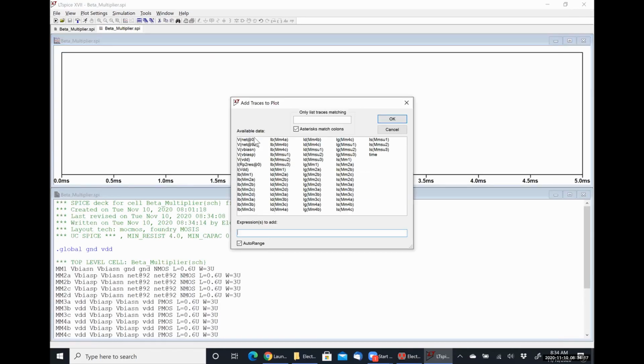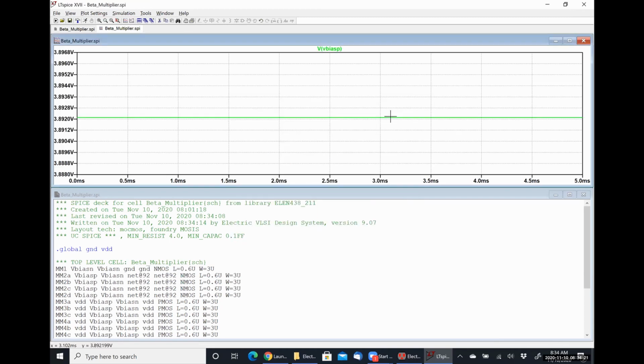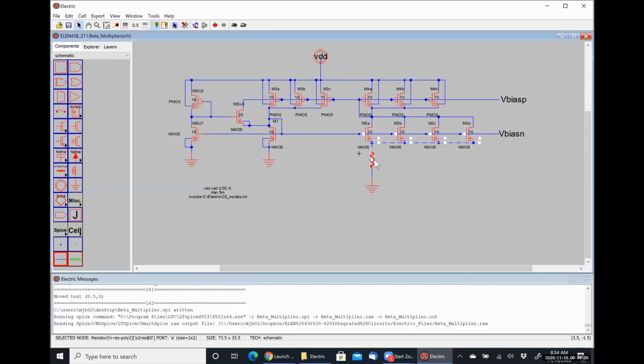I just had to use 14K instead of 15. Okay, so that pulls it up to 3.89. Yeah. All right, so let's back that resistor value off a smidge. And thank you for that catch, Mitchell.